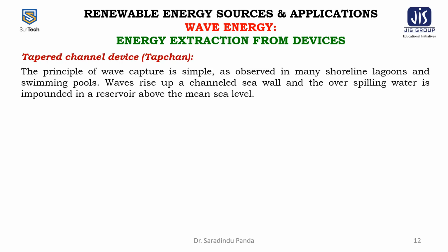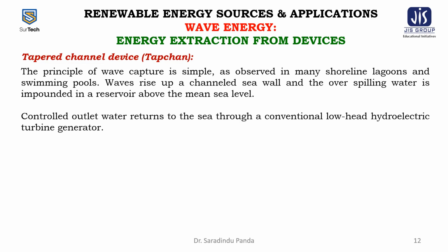Taper channel devices, TAPCHAN. The principle of the wave capture is simple, as observed in many shoreline lagoons and swimming pools. Waves rise up a channeled sea wall and the overspilling water is impounded in a reservoir above the mean sea level.